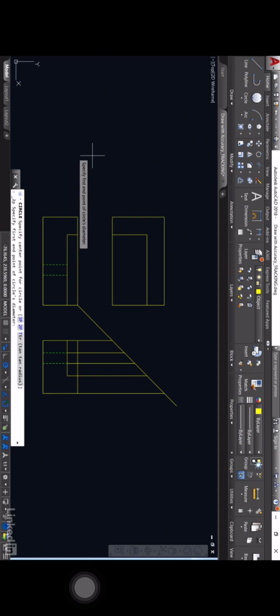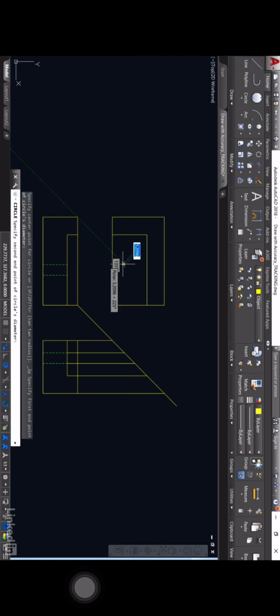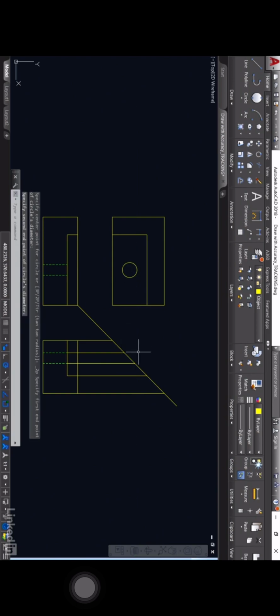If I come up here like this and I hover on that point there and then hover on that point there, as I come across, can you see I get that point there like so? And then what I can do is I can now hover over that point there and hover over that point there. And as I come across, I should get an intersection again. Can you see? And there's my diameter indicated by the orange lines. Click one more time, and there's my circle.